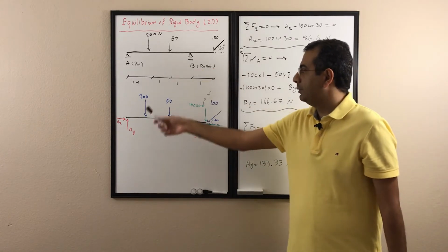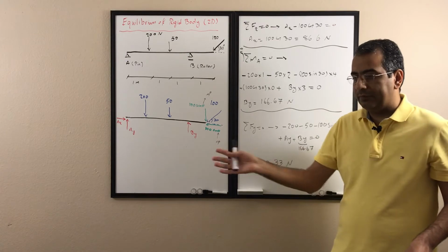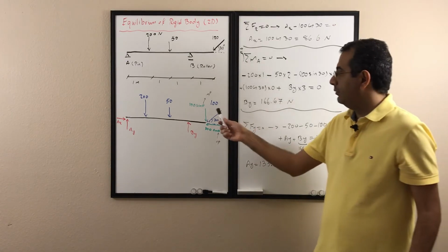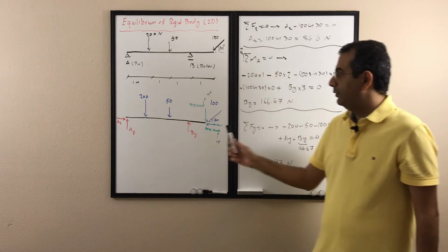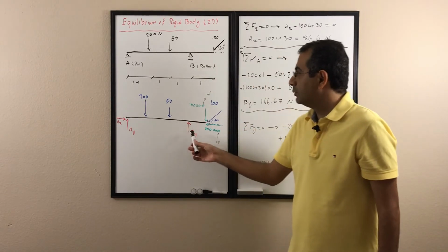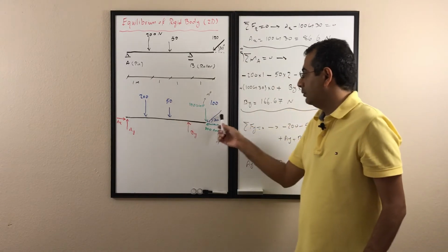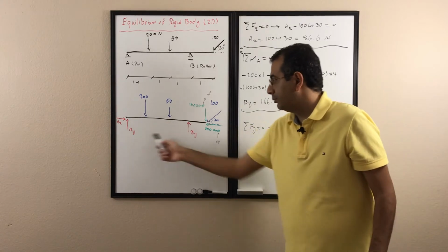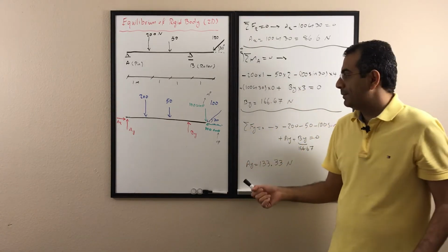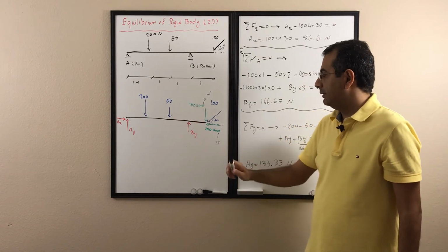So we draw the free body diagram first. In the free body diagram, we draw the object, we remove every connection, any forces. Then we add external forces on that object. Then we add all the reactions from the supports that want to hold the object in place. So the external forces want to move it, and the reactions from the supports want to hold it in place. So we have the object and all the external forces and reactions.